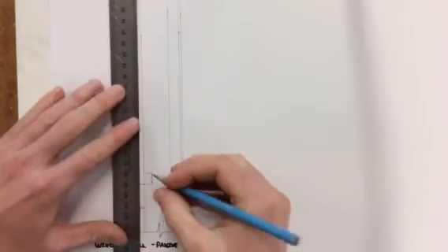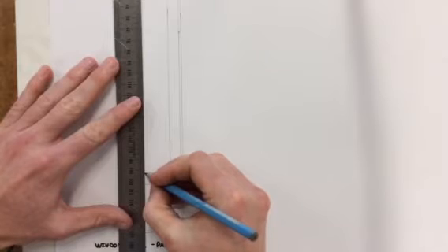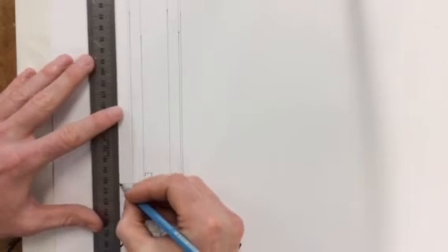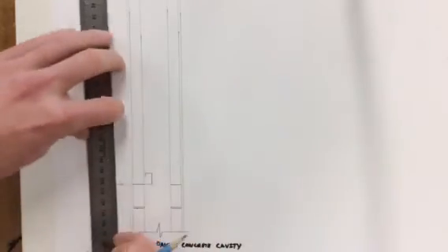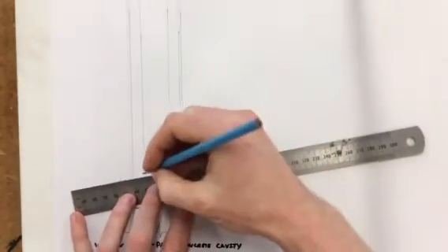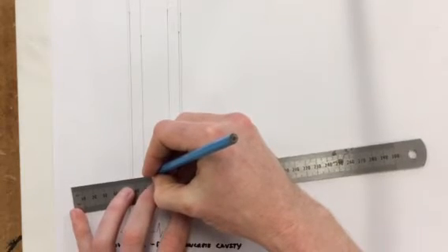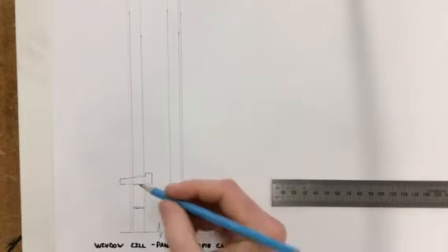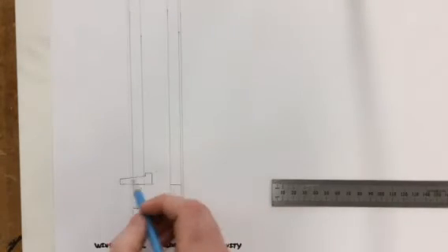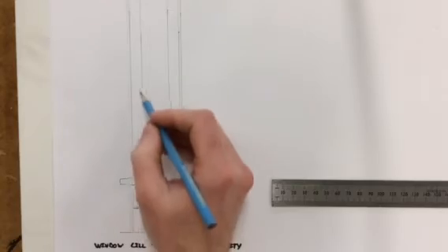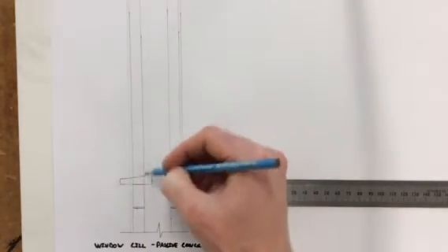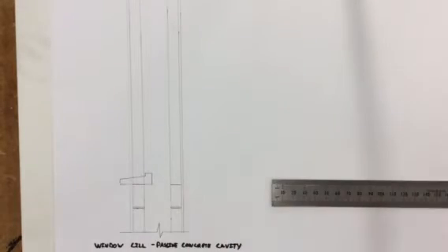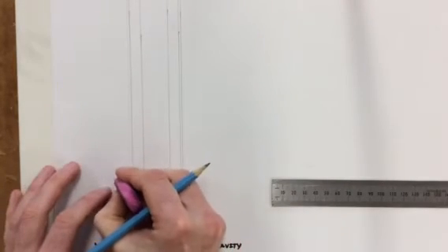This is where our window frame actually sits onto it. Your window frame sits down onto the windowsill, and come down here a small bit. At the front then we rise up 5 mil, and you don't have to be overly sticky on measurements there once you get the profile, something like that. The important point to note is that it has to be sloped down, right? So the rain, you'll see when we finish the drawing, hits the window, comes down, and has to flow away.